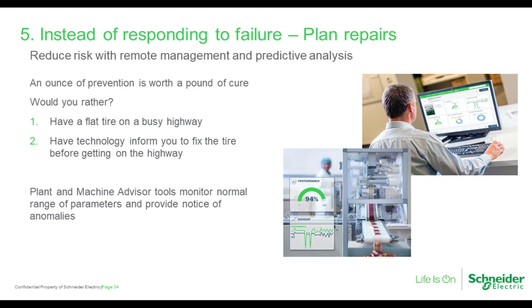So a lot of technologies are out there that can look at not just the rating of the motor in this example, but the typical usage. And they can compare it not only to typical, but typical for this time of day or for this temperature, for example. They start to map out what's normal and what's not normal, and pretty quickly can figure out when something's not right, where the overload is not even coming into play. There's no alarm, there's no warning that we would normally have because we have not been using that kind of intelligent technology until very recently.